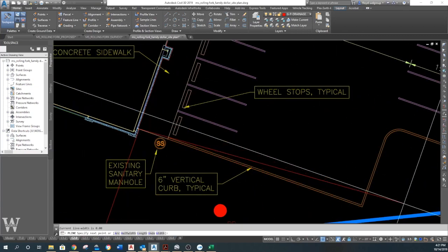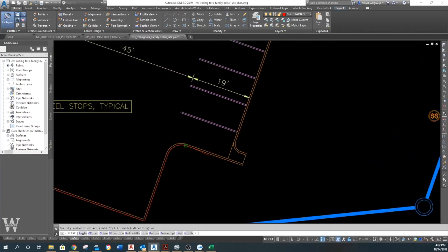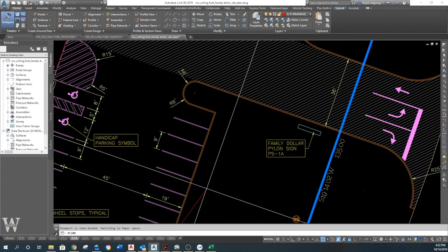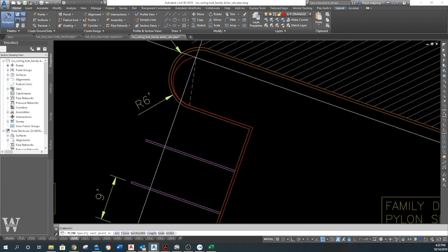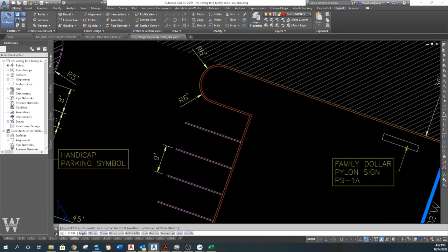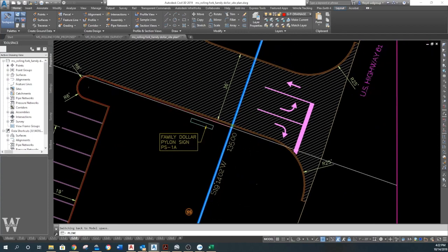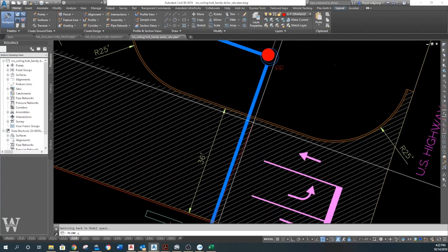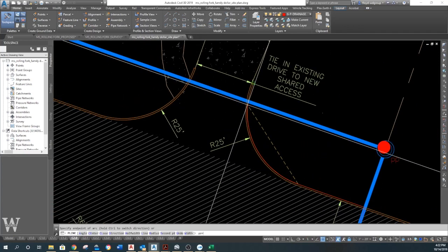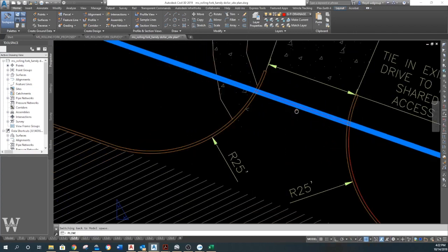So I'm doing a polyline from here to here. That's all lines. If you hit A for arc, it goes right to an arc, and L for line, back to line. Then line, arc, line. Same thing here. We just go to here because the driveways are about the same. I just normally don't do that off the site. That's just the way I do them. Nobody said anything. Hopefully somebody that reviews my plans is not looking at this.